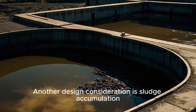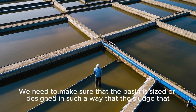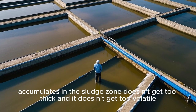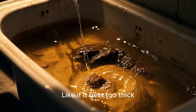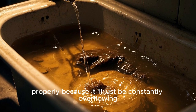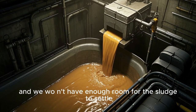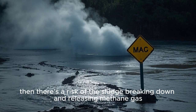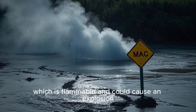Another design consideration is sludge accumulation. We need to make sure that the basin is sized or designed in such a way that the sludge that accumulates in the sludge zone does not get too thick and it does not get too volatile. If it gets too thick, then the basin isn't going to work properly because it'll just be constantly overflowing, and we won't have enough room for the sludge to settle. And if it gets too volatile, then there's a risk of the sludge breaking down and releasing methane gas, which is flammable and could cause an explosion.